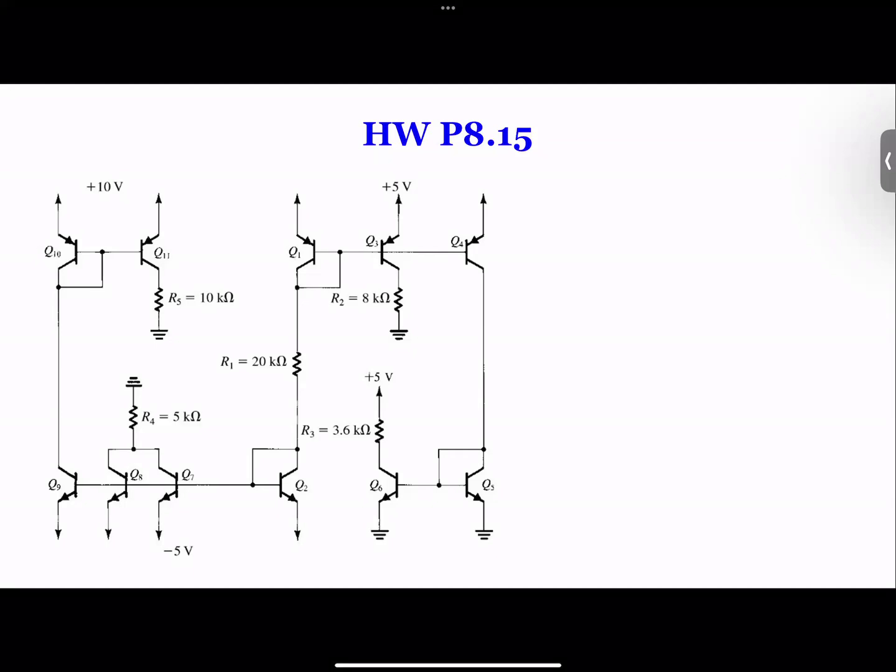But then we find, let's look at which one has its gate connected to the collector. I mean, not gate, base. The base is connected to the collector. If the base is connected to the collector, then it must be a current mirror. In that case, that's easier. Because if you look at this, it's connected and they're back to back, so this is going to be a current mirror. That's what we have. And then we have a resistance over here.